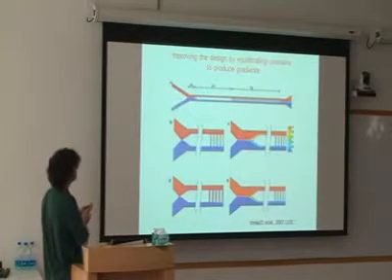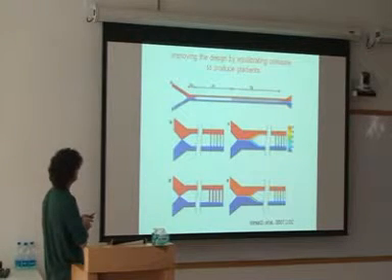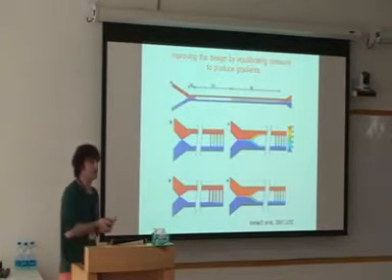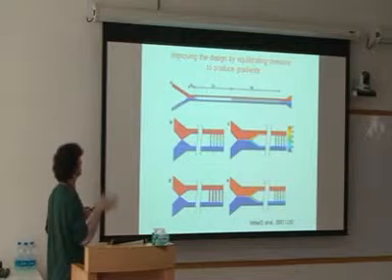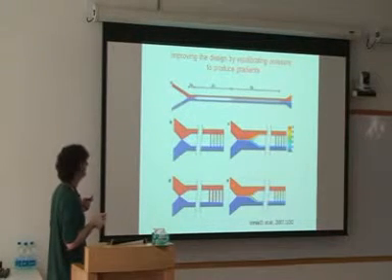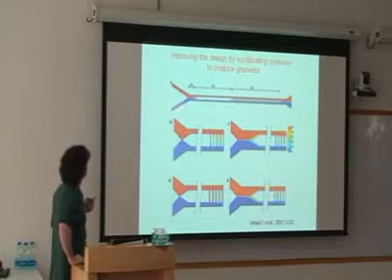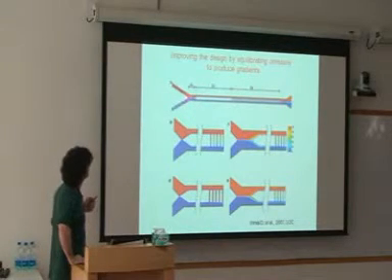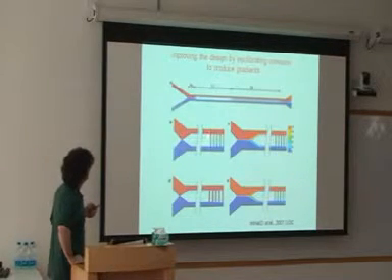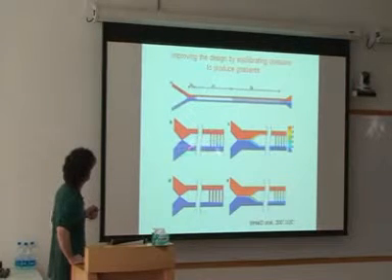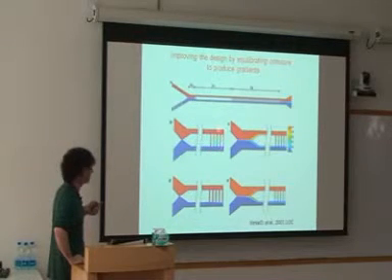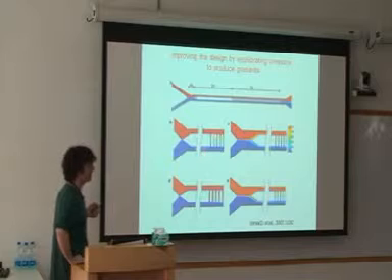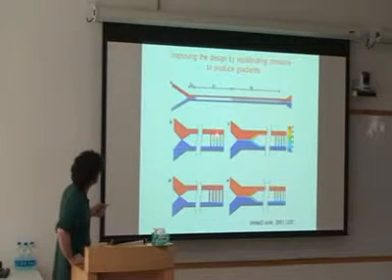So this example, when you're starting to work with microfluidics, the problem often is to control the pressure in the device. And so you have sophisticated ways of doing it with devices which give you very fine pressure control. But for example, when you're running this sort of channel, let's imagine that here it's completely separated, okay? And you have this small channel in between. If you're flowing things here, if you have a very small difference of pressure on both sides, you will start to have flows in your channel here. Okay? And that would kind of be bad for what you want to do, in particular if you want to generate gradients in the small channels.